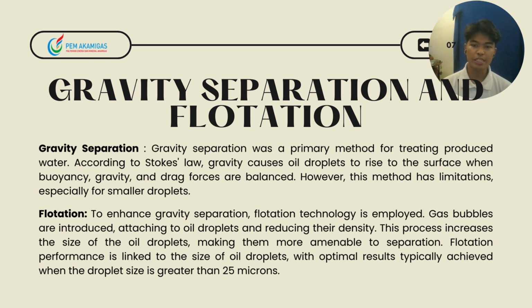And then flotation. To enhance gravity separation, flotation technology is employed. Gas bubbles are introduced, attaching to oil droplets and reducing their density. This process increases the size of the oil droplets, making them more amenable to separation. Flotation performance is linked to the size of oil droplets, with optimal results typically achieved when the droplet size is greater than 25 microns.